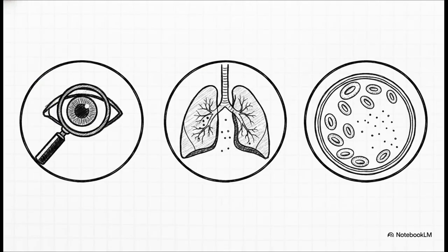Now, a really crucial point here is understanding what those PM or particulate matter values actually mean. PM10 refers to particles that are less than 10 millionths of a meter in diameter. They are literally invisible to the naked eye. PM 2.5 is even smaller, less than 2.5 micrometers, and it actually makes up about 70% of the total PM10 in our ambient air. Why does that matter?